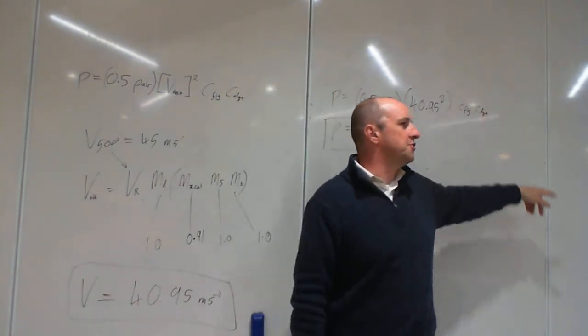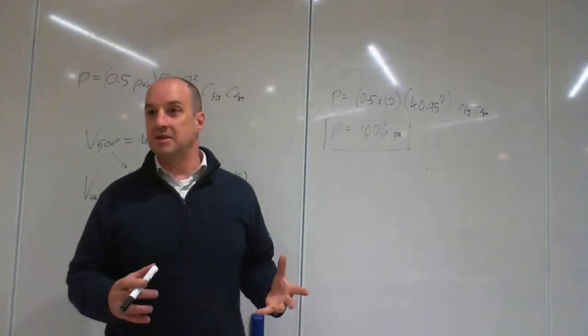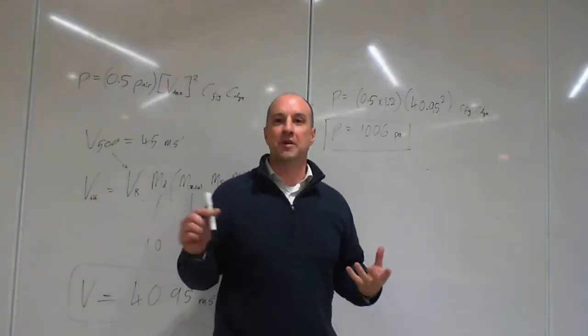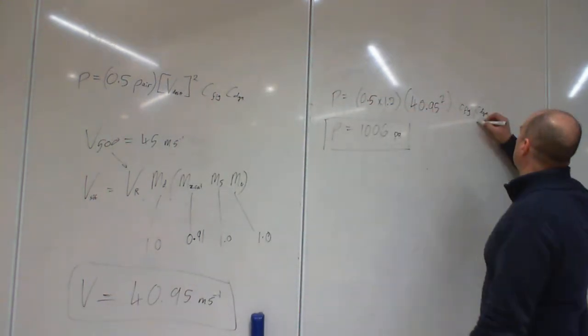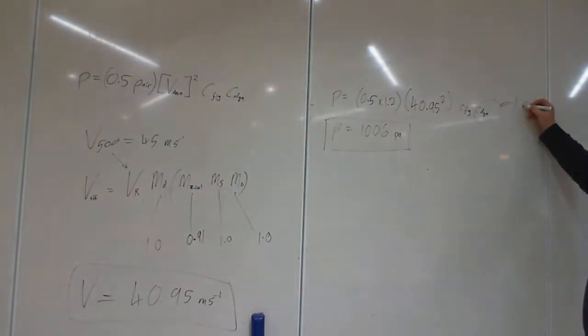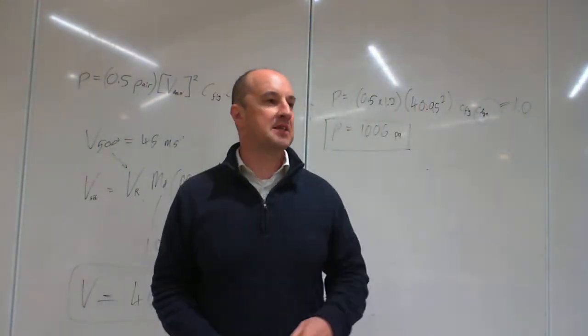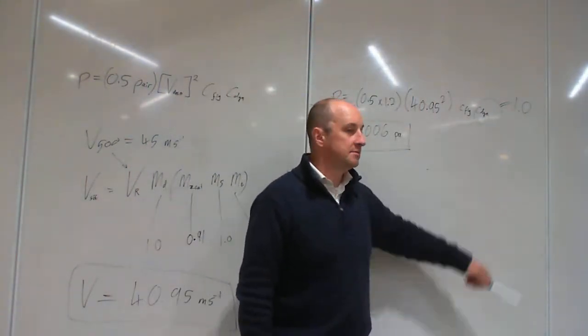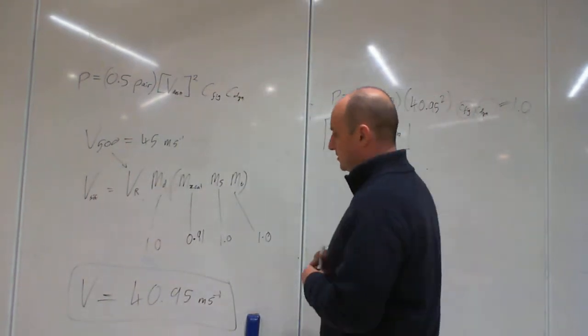It's for people who have access to wind tunnels to back up their stuff. It's because you're talking about the structural rigidity and flexibility of buildings and how they sway back and forth and how the eddies go around that. So, for the vast majority of your life, that equals 1.0. Okay? Unless your structure is big and flexible, you don't need to worry about that. Happy days. All right. C fig is what we're going to talk about. So I'm going to rub this off.